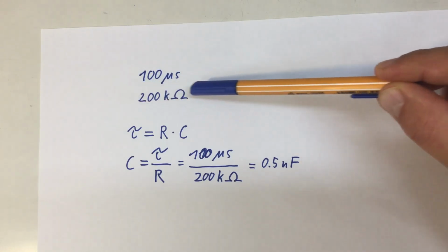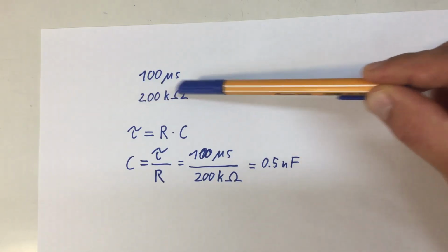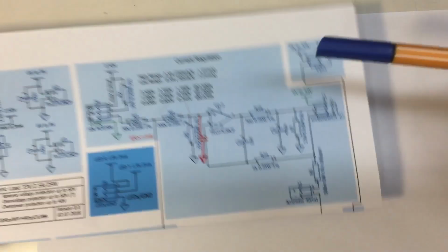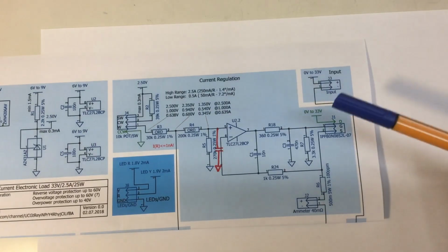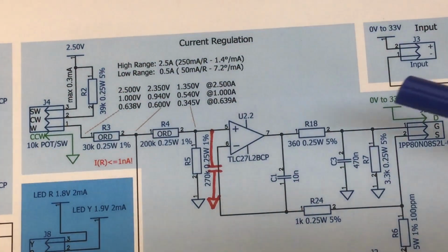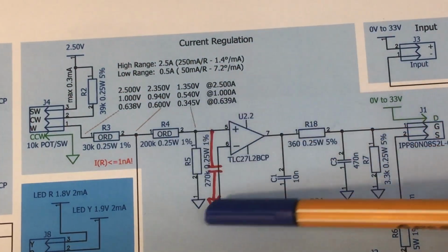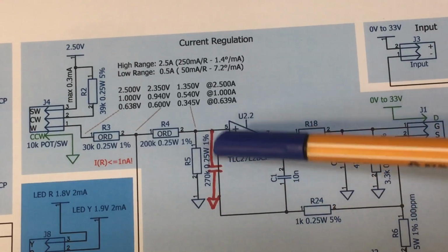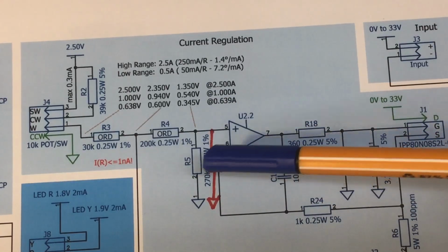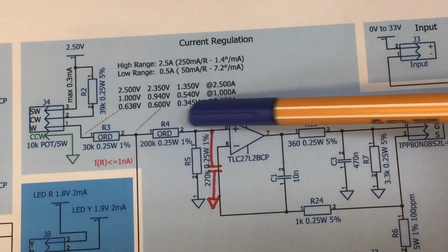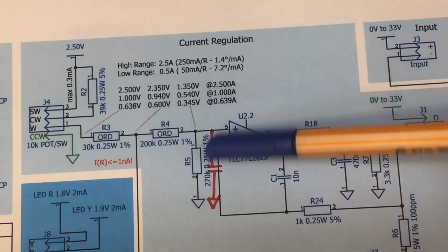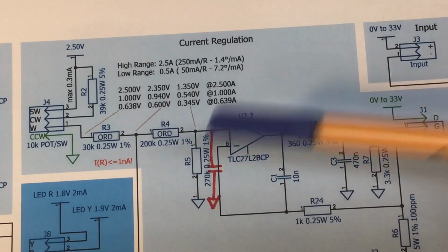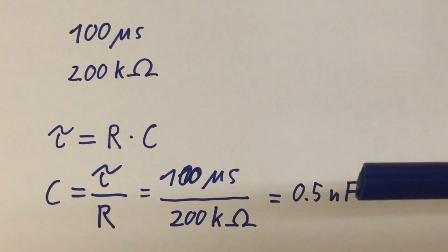Our resistor is, order of magnitude, 200 kiloohms. It depends a little bit how you take that as an RC element. In a parallel RC element, that R5 has 270K. If you look at that as an RC element, that has 200K. So order of magnitude 200K.